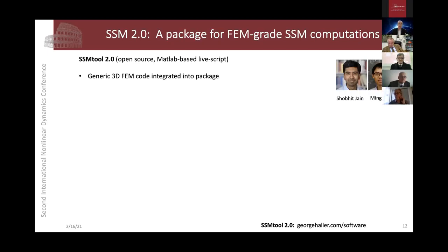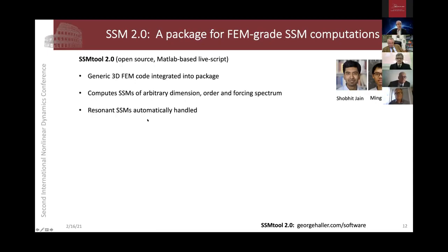The finite element code provides the nonlinear coefficients for the actual SSM computational tool. It then computes SSMs of arbitrary dimension and order, and for arbitrary forcing as well. And it handles resonances. Whenever you have resonant modes, it will automatically not be a 2-dimensional SSM, but a 4-dimensional or 6-dimensional one, because you want to include the resonant modes. That's also built into the code.